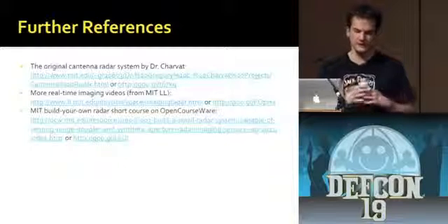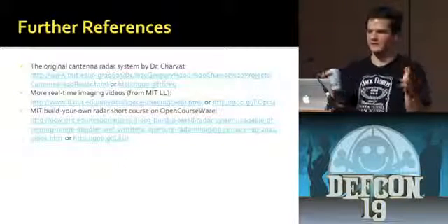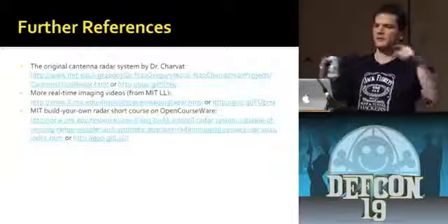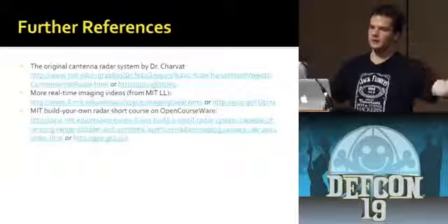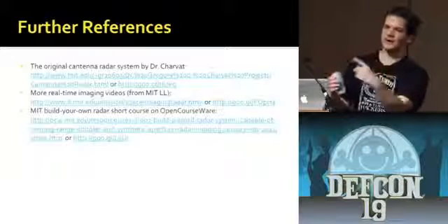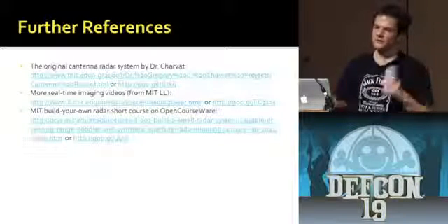You basically get different characteristics. So if you're trying to do the SAR imaging, having a wide beam width is actually somewhat useful because it decreases some of your spatial fidelity, but you also get a wider image. If you have a very narrow beam, you're not going to get any signal from something that's further apart. So it's a trade-off there.